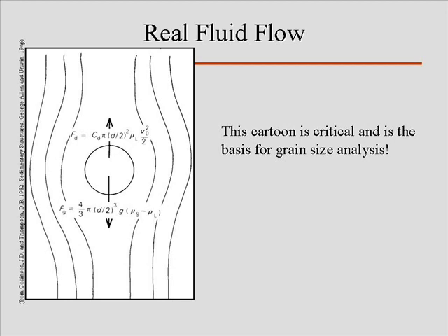The one on the bottom, F sub g, is the force of gravity, modeled under these characteristics upon a particle. This is the drag coefficient, or the force of drag. What you're looking at now is a grain that is sitting in a fluid. The fluid may be air, the fluid may be water. If you have this thing drop, there's a force of gravity accelerating in this direction, but there's the force of drag that is slowing it down, and they bounce off of one another.